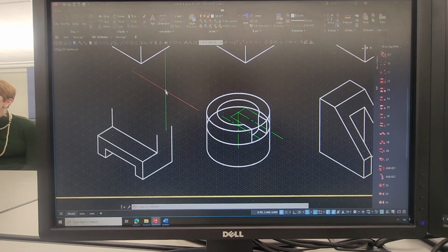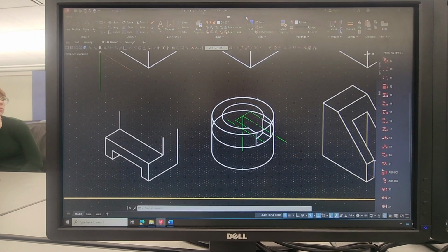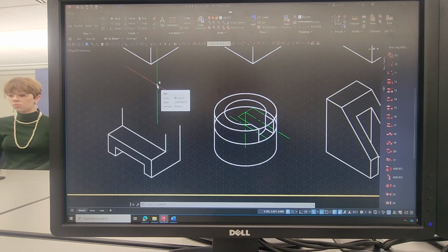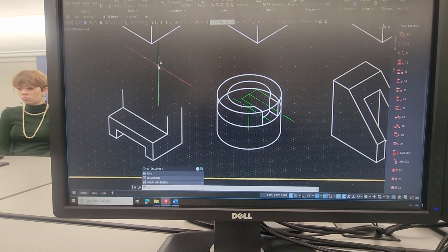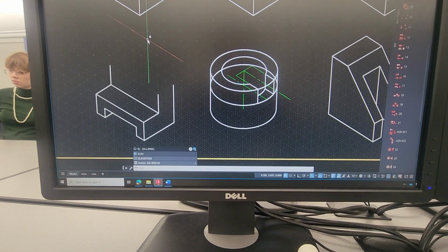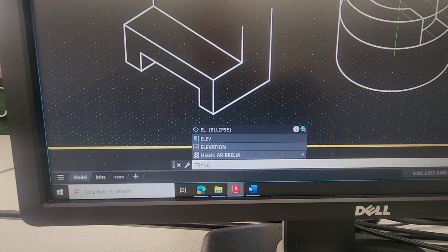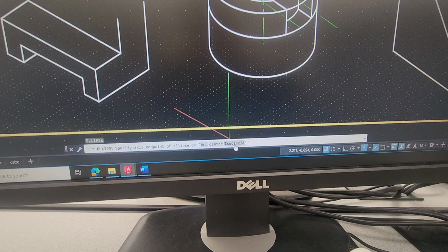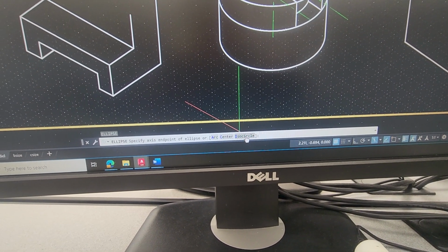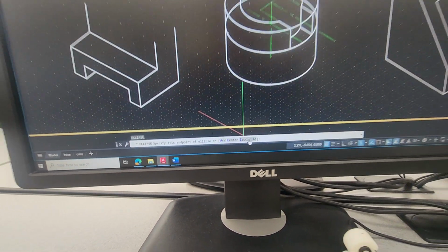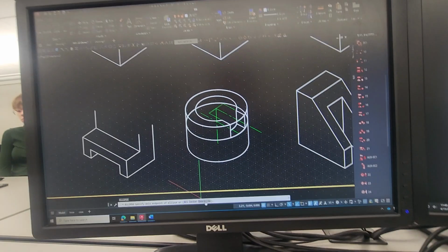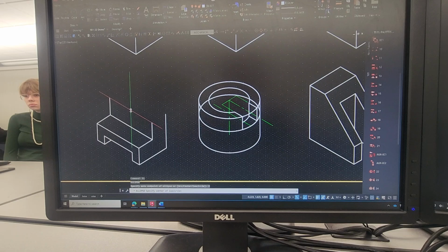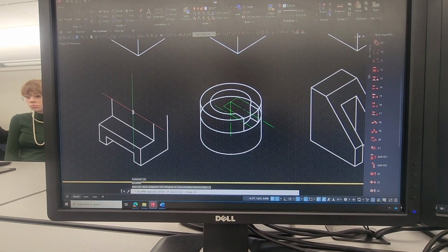And they're found in only one place, and it's not even a button up here we can push. It's actually in the ellipse command, but it's only available by typing EL at the keyboard. See down there at the command prompt, I type in EL for ellipse. Now when I hit enter, I see I've got an option called isocircle. So in order to make a circle, I must go to the EL ellipse command, choose isocircle, and it asks where I want to start. I'm going to choose that grid spot right there. I'll turn my F9 back on, and then it hops right to that point.